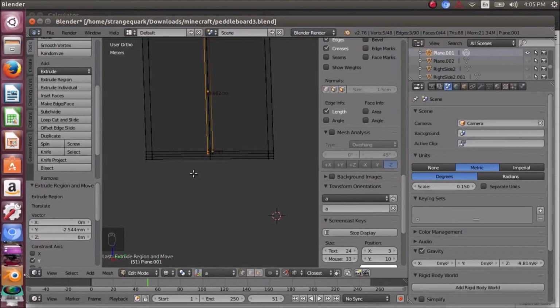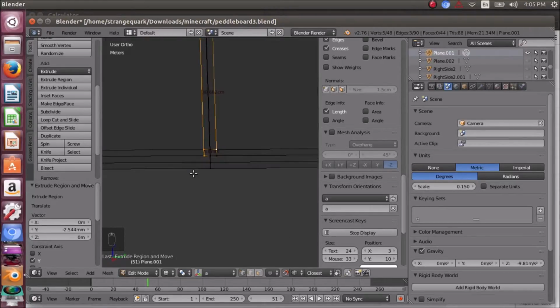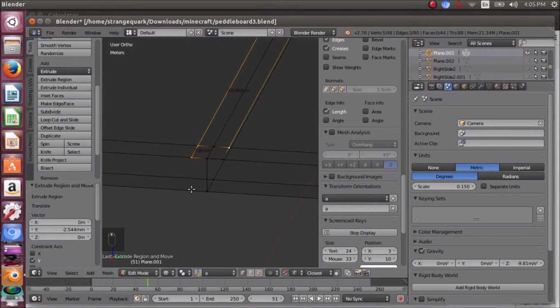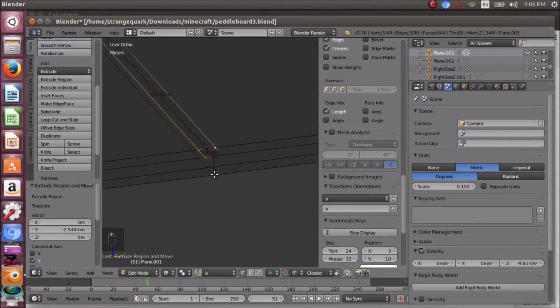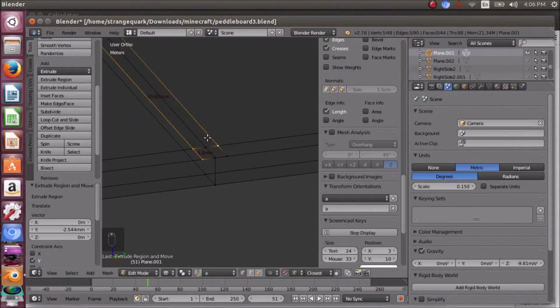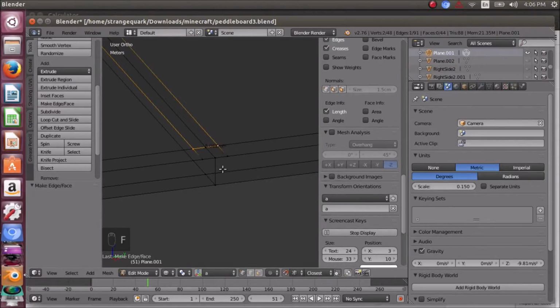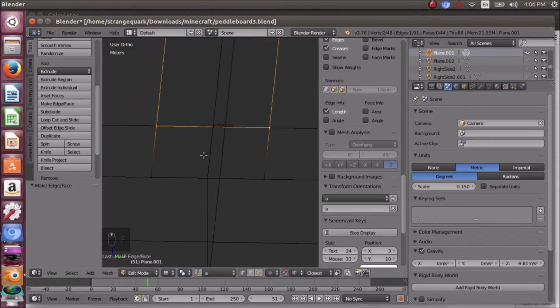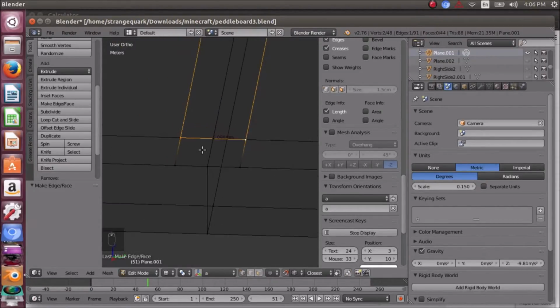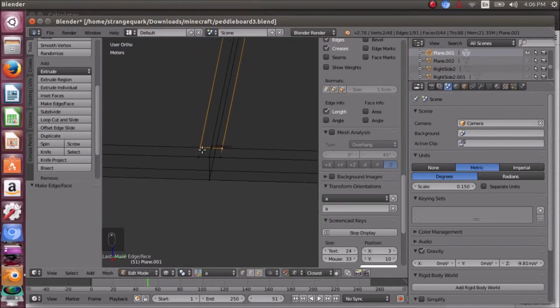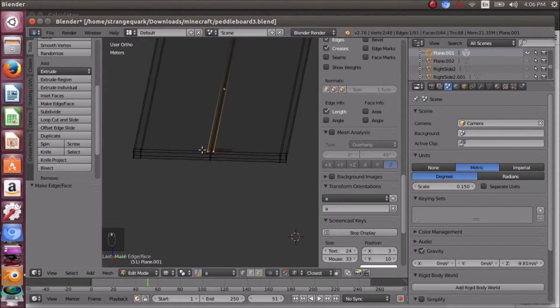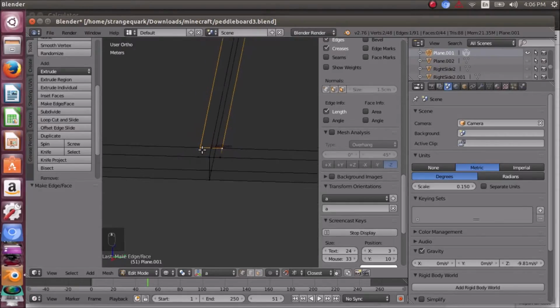Now, I don't think I actually incorporated anything like it, but anyways, this total length, if I take this vertex and hit F, the total length should be 5.08, and it looks like it is, so we're slightly off, 5.088 millimeters, which is actually 5.09 millimeters, so we're off just by 0.01 millimeters, which is a very, very small difference. So small that I probably will ignore it, even with the roundup consideration there.